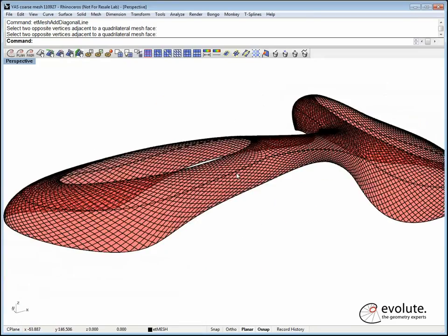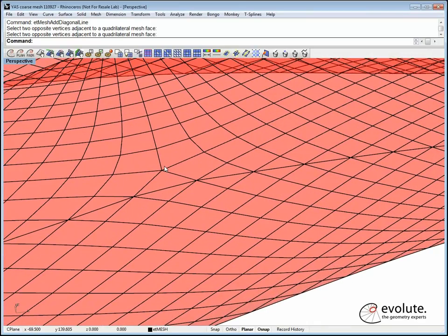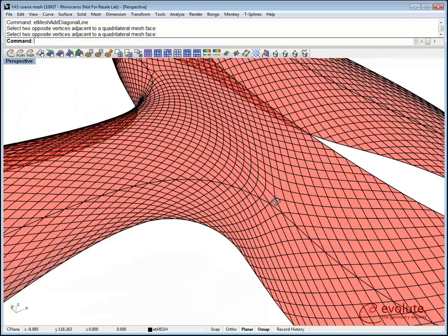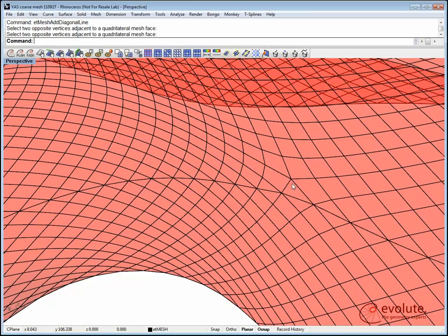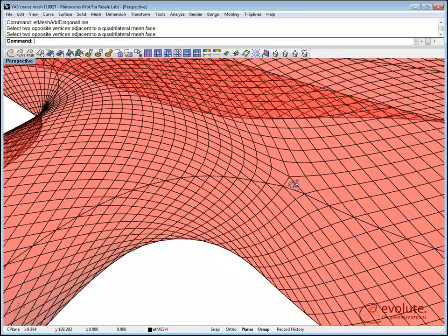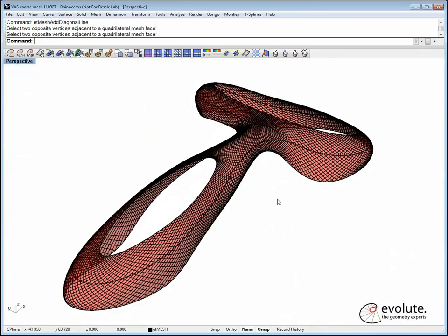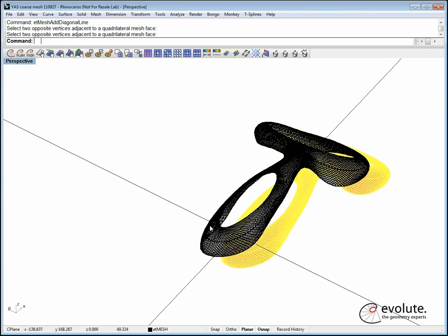that actually has a different singularity layout. As you can see here, we have a singularity here. We have some valence 5 vertices on the grid shell, and we will try to see if a different connectivity of a different coarse mesh works better. Again, we have a valence 5 vertex here, and almost mirrored to the other side. So I will just put this optimized mesh aside for a bit.